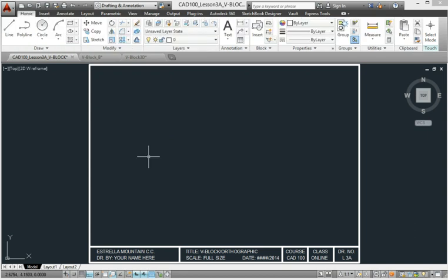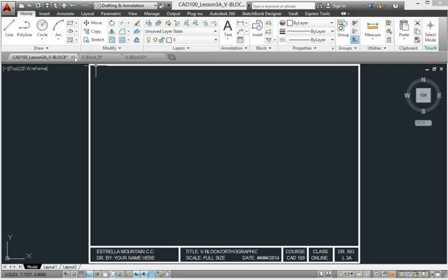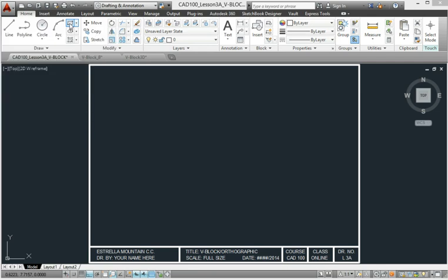As you recall, the first step is to draw 3 rectangles that represent the front, the top, and right side views according to the height, width, and depth of our block. The measurements of our drawing. So let's do that. Let's try a new command called rectangle to give you new options to work with. Pick a lower left corner, drag to the upper right.